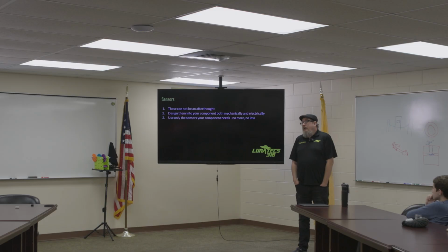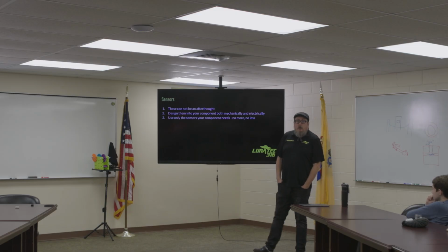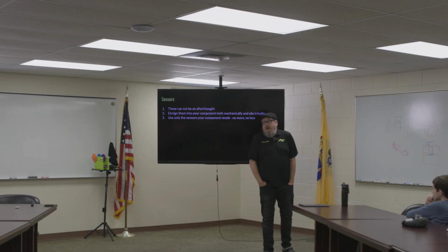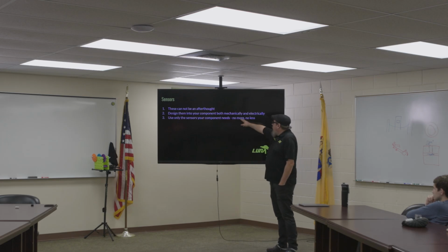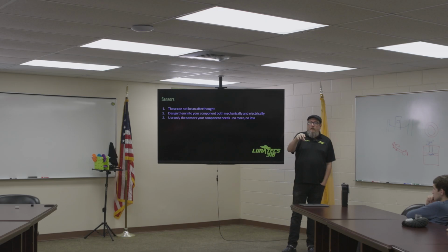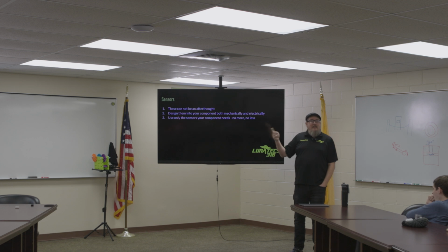And if we're spending three meetings figuring out where a sensor goes, what are we not doing? We're not programming, right? Because we need that sensor. So we need to be very deliberate about where we put our sensors so that mechanical and electrical can be deliberate about building them there. And I know that sounds weird, but the reality is if there's not a sensor where we need a sensor, you need to run electrical to that sensor. You need to run the CAN network to that sensor.